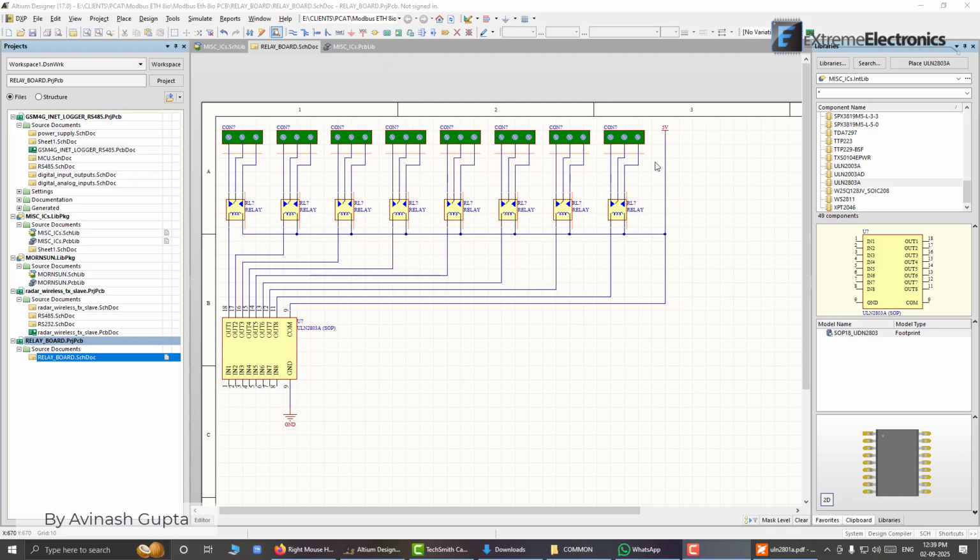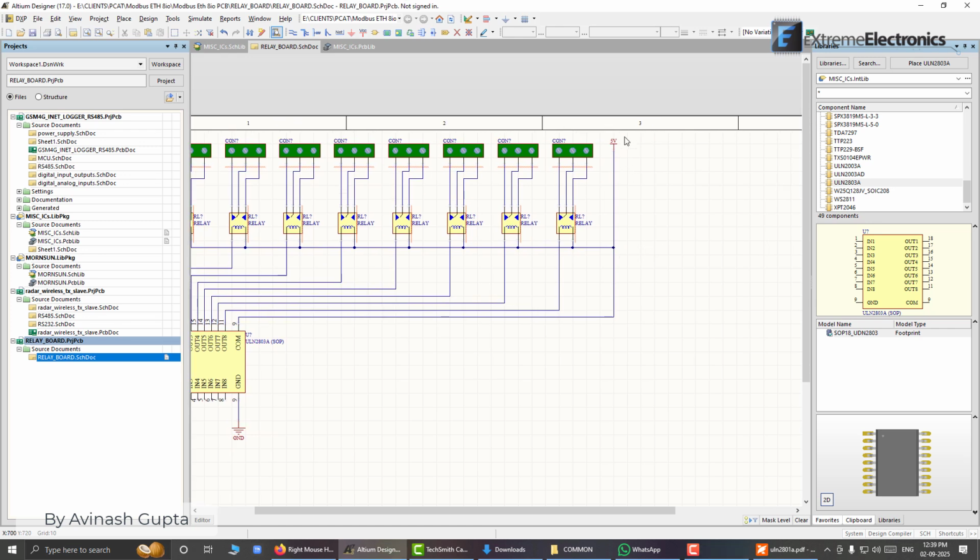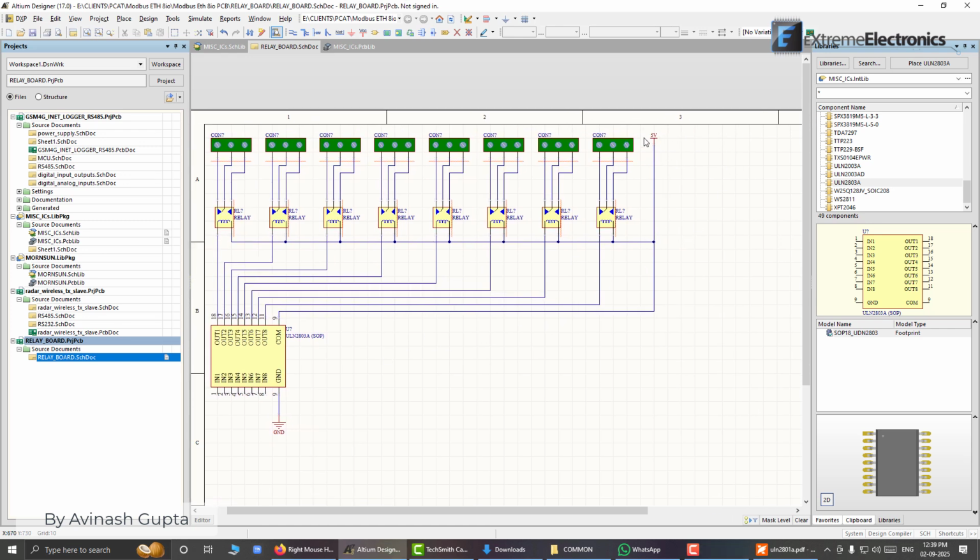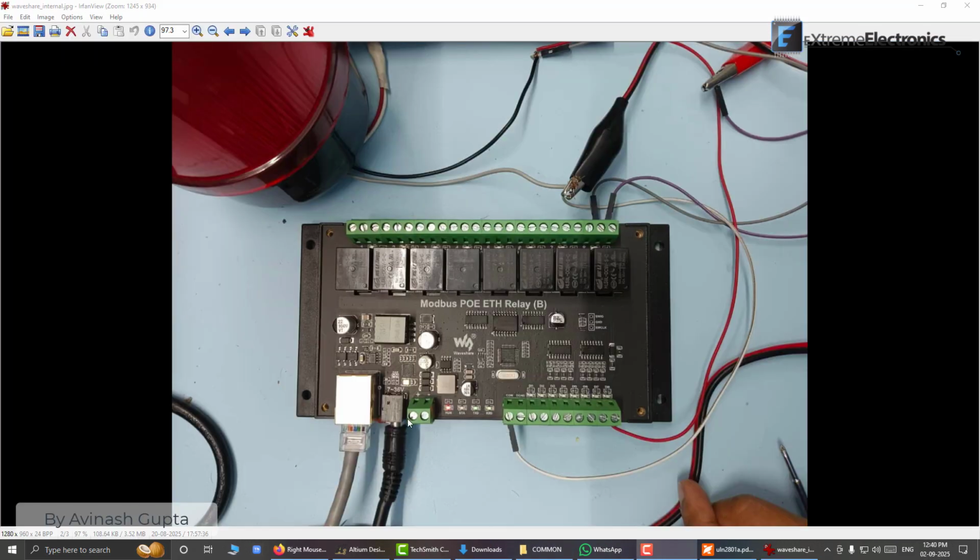And now you have to understand one important concept here. So we have placed a symbol for VCC and a symbol for ground. These are not going to magically generate 5 volts somehow. These are just plain names given to this net. So a net means the connection. So somehow you have to create some means to generate this 5 volt. So this could be something like this. We can have a connector here. And this could be something like this DC jack where the user can plug a 5 volt supply, or a screw terminal like this where the user can screw up the wire from the power supply. So we have to provide this.